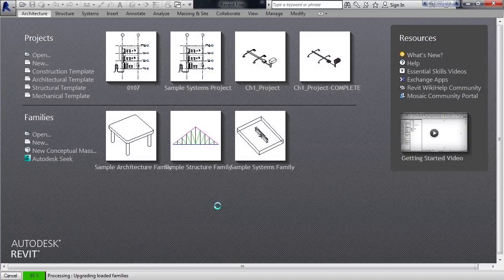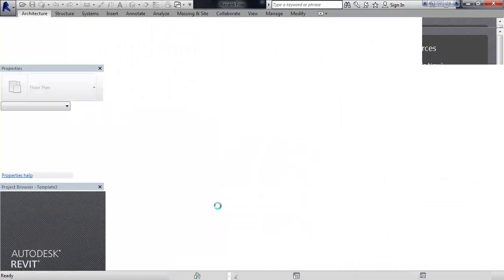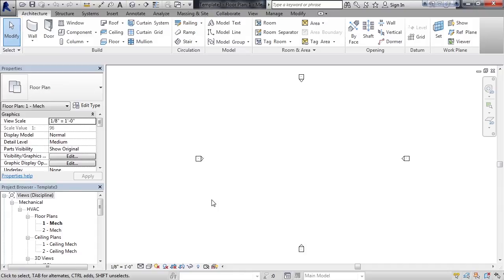And then it's going to open up and I'll see that template with all of its functions and all of its settings, and I can go in and start to make any modification I want. Now, once I save that template, it will be saved back to the 2015 version. There is no saving back to previous versions in any flavor of Revit. So once you open and save something in that version of Revit, you have to work in that version or a newer version.